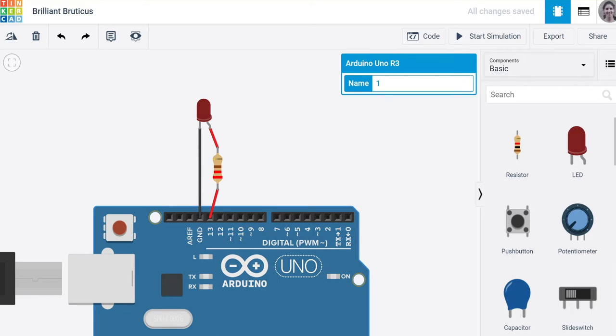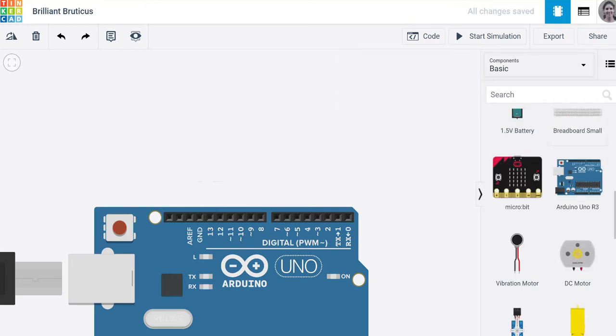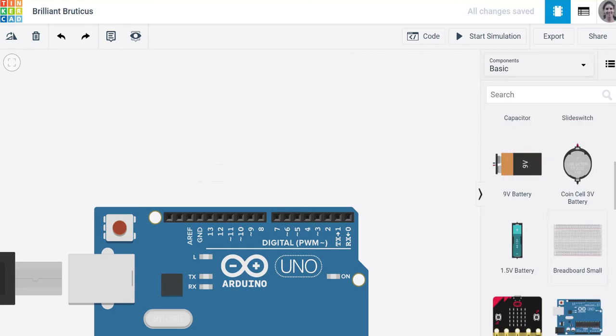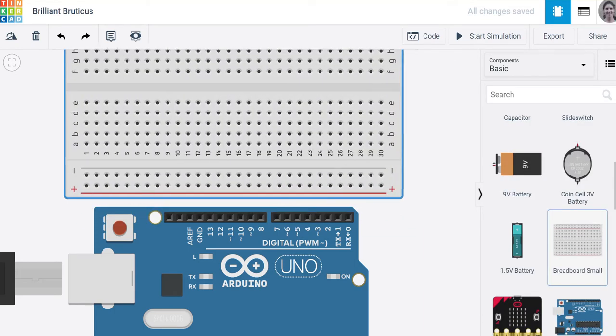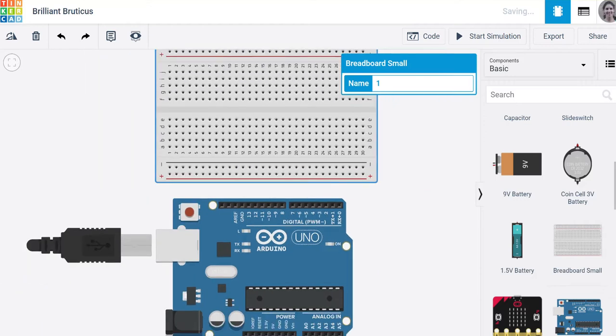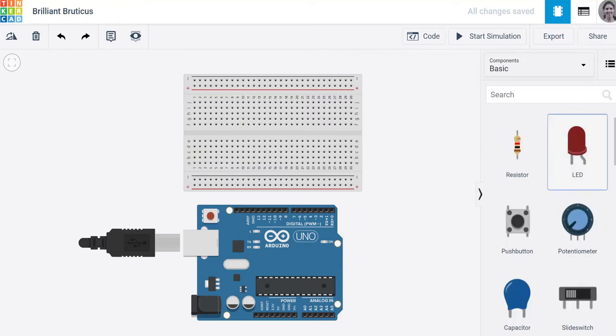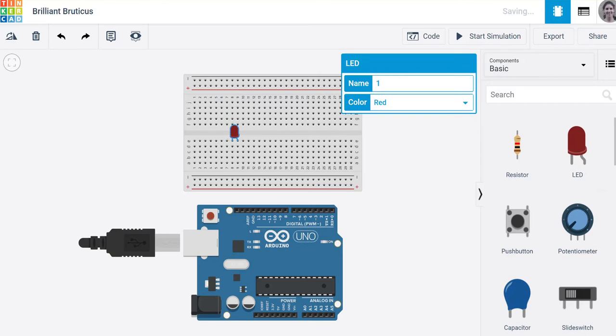So instead of adding just the LEDs and having a lot of wires, we will delete everything and we will add a breadboard. Remember this breadboard there? We used that last week. So we take the breadboard and we'll put it on top of the Arduino. That will be really useful. That will remove some wires. Okay. And we want to have 3 LEDs. So scroll up. Let's add a red LED anywhere you want in the row E.